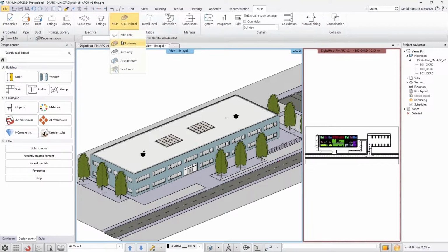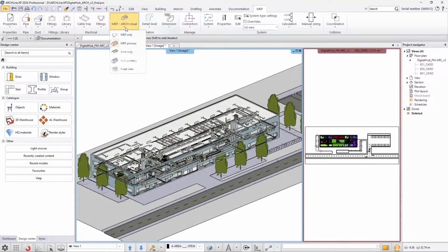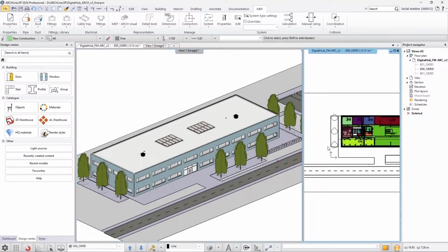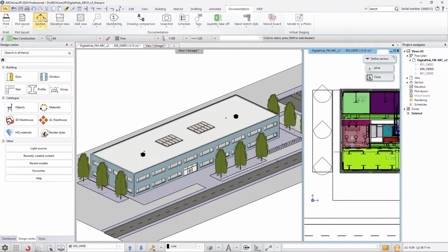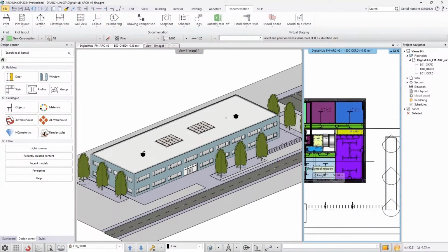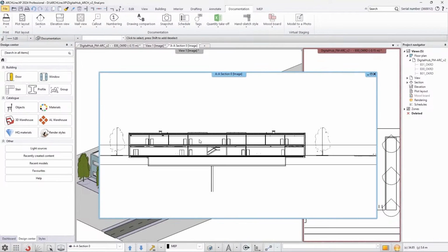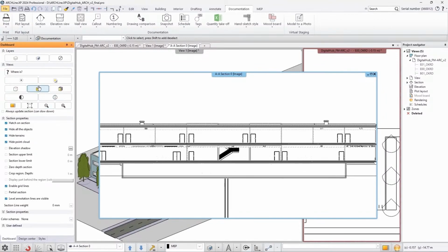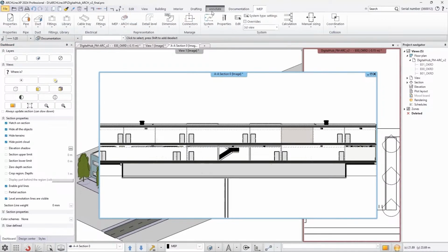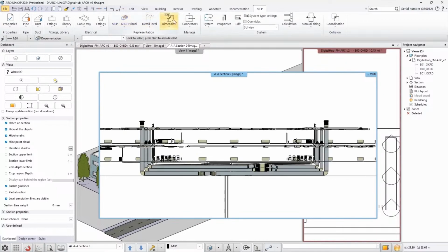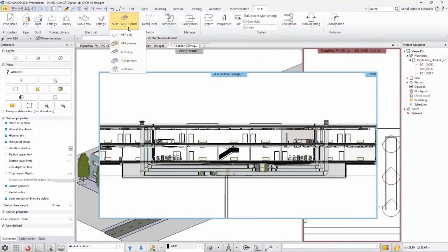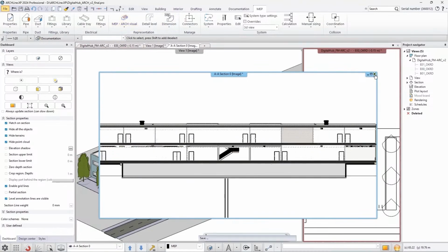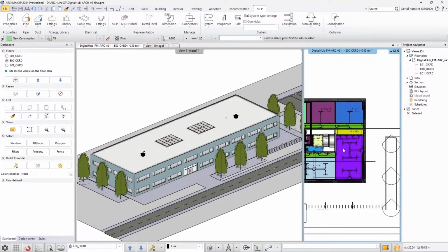Data transfer between BIM programs is possible using the IFC format. Import the MEP plans as an external reference for the building model in several steps: heating, air conditioning, water pipes. The 3D model of MEP services then allows all MEP services within the architectural and structural constraints of the building. It is a very important part of the process, as it lays the foundations for many construction-related plans, sections, and elevations. It can also be used to create a detailed overview of the building.